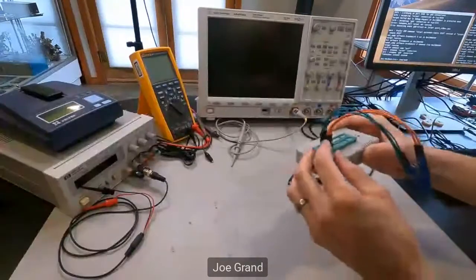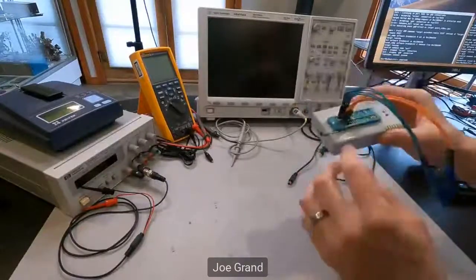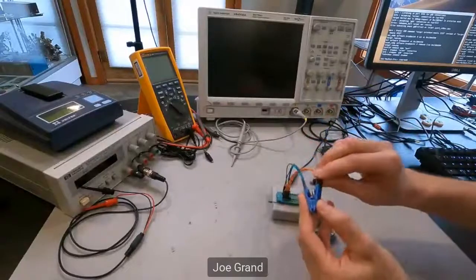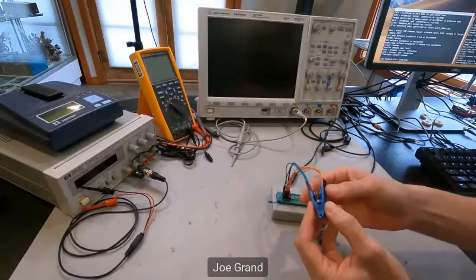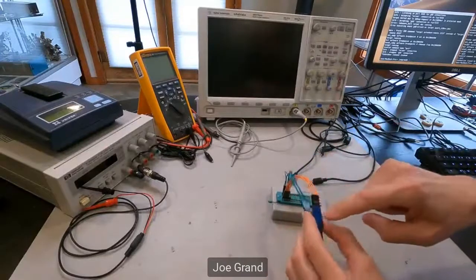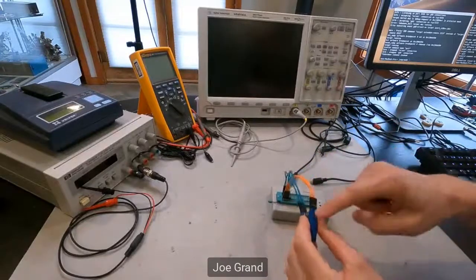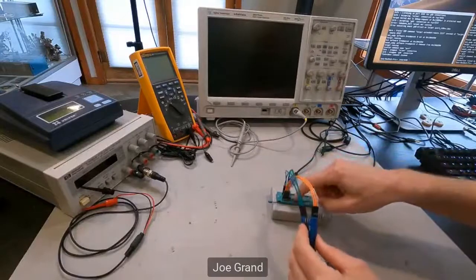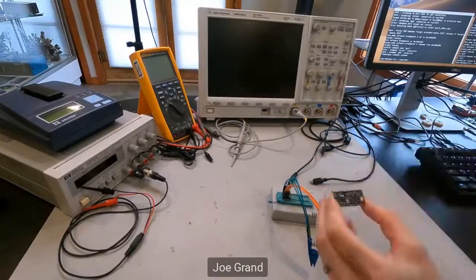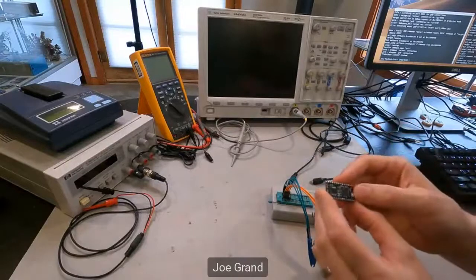So I have a little hacked together adapter here, which has this little clip. This clip is called a DIP clip or an SOIC clip. This is going to clip on directly to my target chip. And then it's just a one-to-one matching of the pins from the chip to the device programmer. What I'm using for our example here, I could have done it on any of the other ones, but I thought it'd be fun to use different stuff.